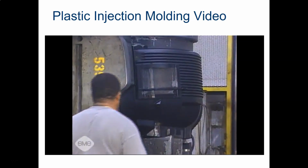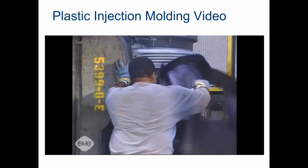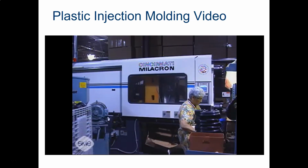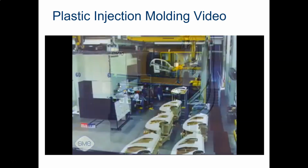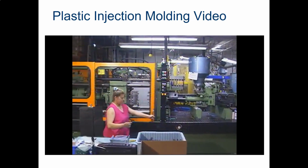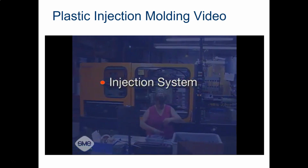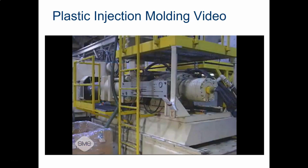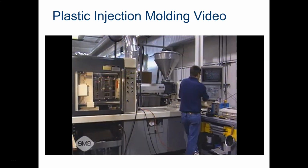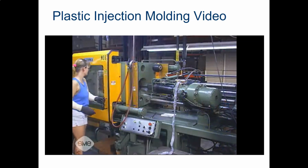No other manufacturing process offers the range of capabilities injection molding provides. Injection molding machines range in size and complexity from desk-size units up to machines the size of a small house. All injection molding machines are a combination of two systems: an injection system and a clamping system. The injection system heats the thermoplastic material to its appropriate viscosity or flowability and then forcefully injects it into the mold. There are two types of injection mechanisms: the reciprocating screw, which is the most common, and the two-stage screw.